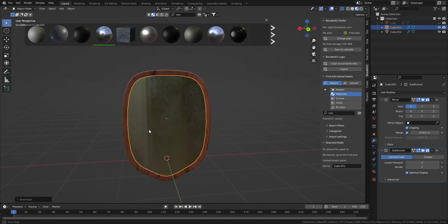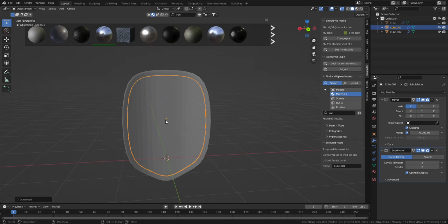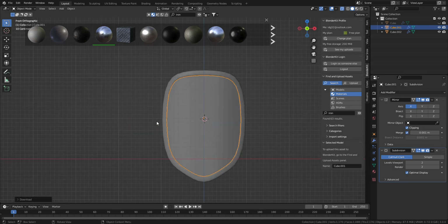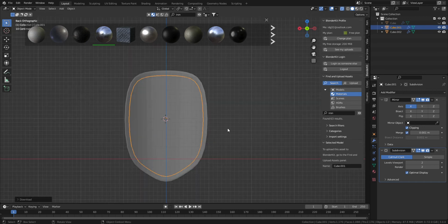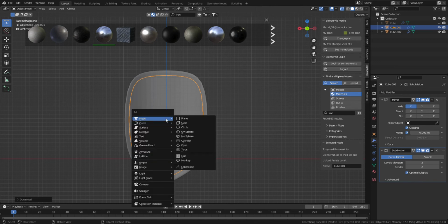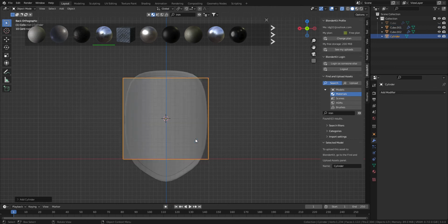If you want to make a handle, that's easy. We go back to regular shading mode, click in the center. Let's see. Control 1 to go onto the back side, click center right, shift click. I'll do Shift A, insert cylinder, turn off X-ray.